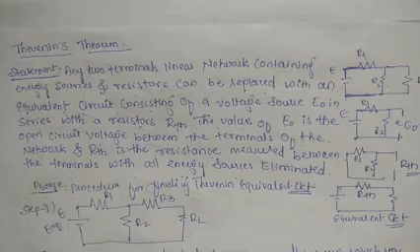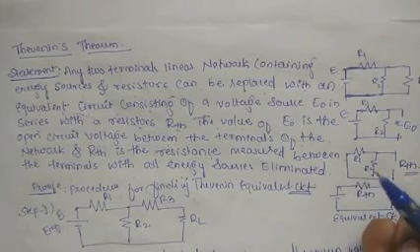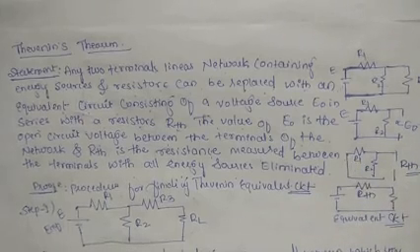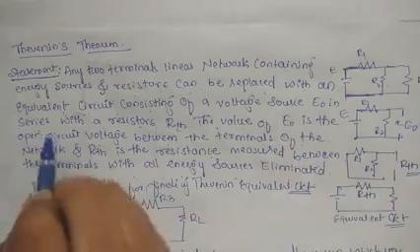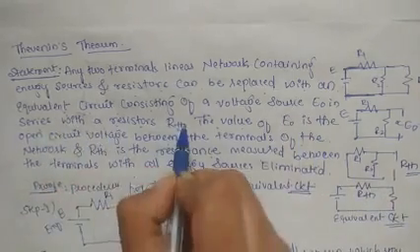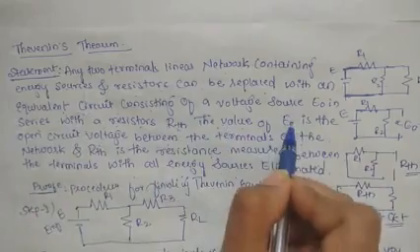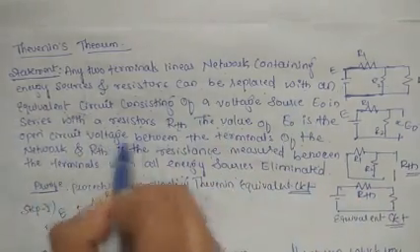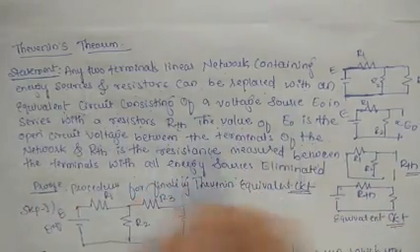How to calculate the value of E0, we can identify in the further proof, but I am explaining it in a simple way. Series with the resistor RTH, the value of E0 is the open circuit voltage between the terminals of the network.